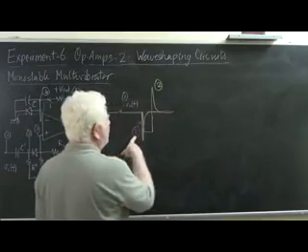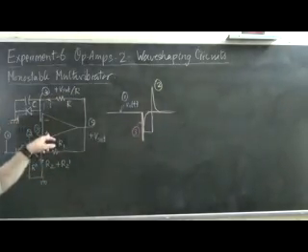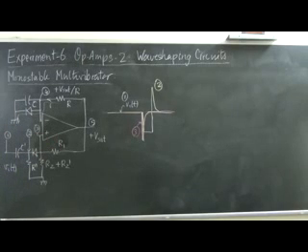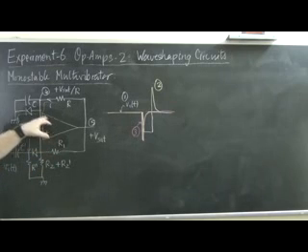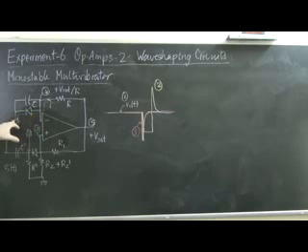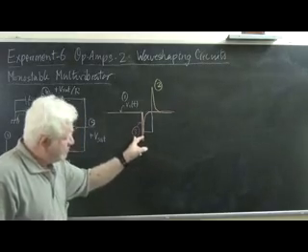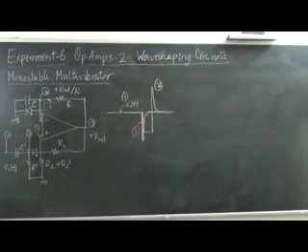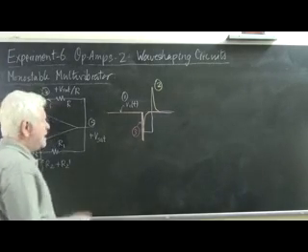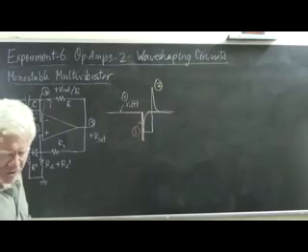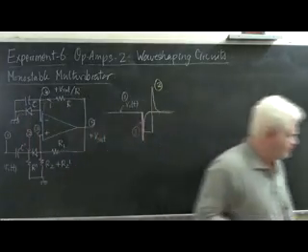This pulse, waveform 3, is experienced by the non-inverting terminal. This non-inverting terminal, which was literally at 0 volts because the diode was forward biased and shorting the inverting terminal to the ground, now goes below 0 because of this negative pulse, waveform 3. This negative pulse therefore causes the op-amp output to switch to minus Vsat. And temporarily we observe what would happen to waveform 5.